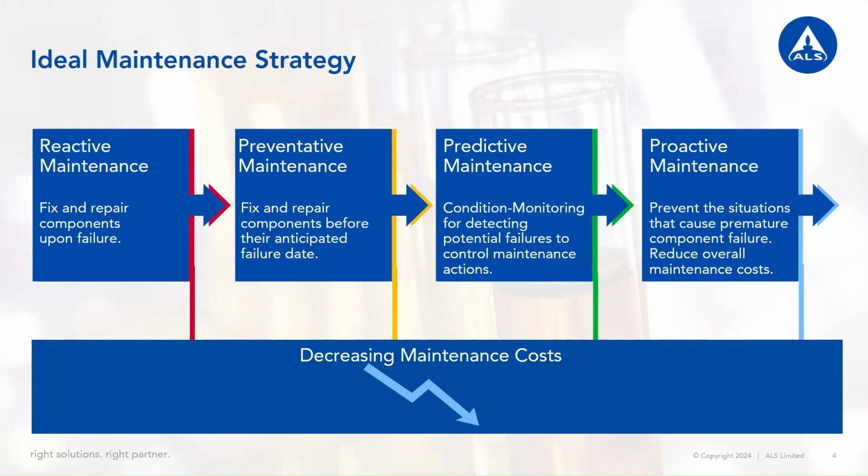Preventative maintenance is doing maintenance on a time-based schedule without monitoring the equipment's condition. A good example would be getting your car's oil changed every 5,000 miles. People typically don't get their oil tested and just trust that the oil change is all they need to do. Like reactive maintenance, this strategy is not ideal for anything that will negatively impact the business if it fails. There are many unknowns that are not accounted for if you're not monitoring the internals of your equipment.